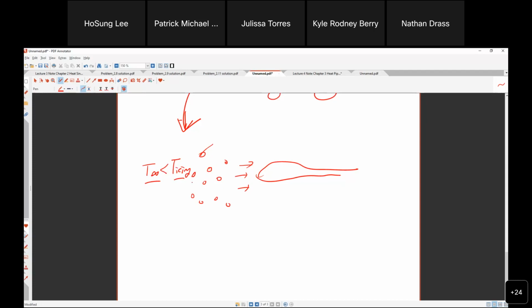So it may freeze, maybe. But what happened is the surface tension: with such a small radius, P1 minus P2 is 2 sigma over R, and with R in microns, the pressure difference is huge, so the pressure inside is high. Even with icing temperature outside, inside, because of the high pressure, it can remain liquid. It's just physics, thermodynamics, because of pressure.